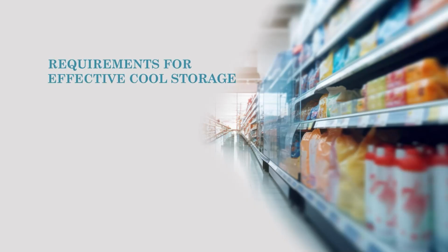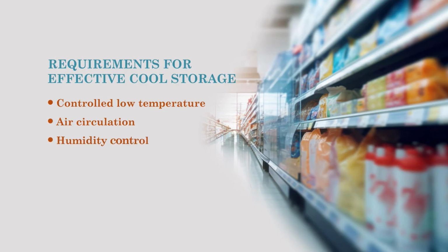The requirement of effective cold storage or low temperature storage will mainly be a controlled low temperature, along with air circulation, because food is generating heat. Are we able to take that heat through air circulation quickly away from the food or fruit or fresh harvest? Humidity, that is RH. Then the gas atmosphere is also sometimes played with to control the respiratory rate.